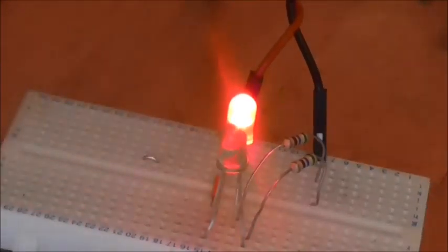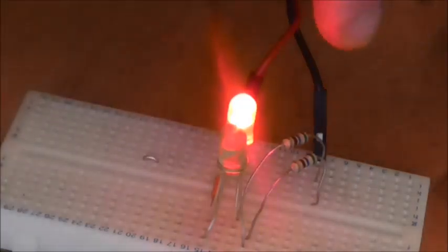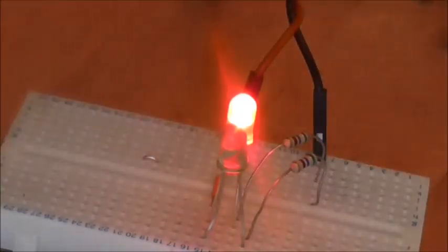And the 540Rs are limiting the current, whatever the voltage, and it will do between 3 and 15 volts, and that's as far as I've tested it. It'll probably go up to 18, possibly even 24, but I can't guarantee that, I haven't tested it, thanks to these 540 ohm resistors, rather than the 160 or 200 or whatever we'd put in if we were following the mathematical guidelines religiously.